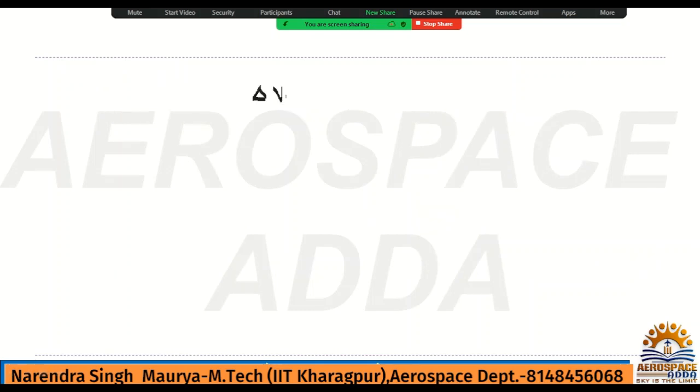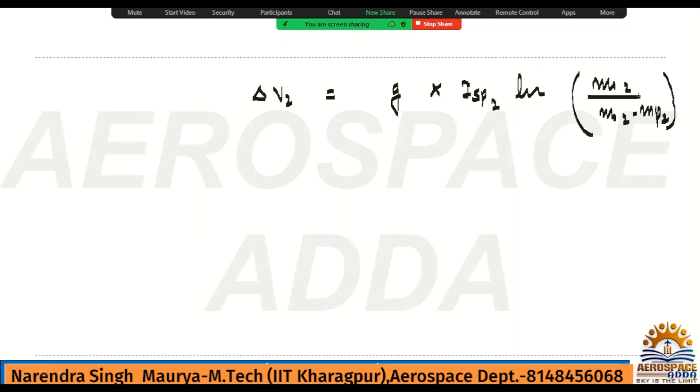Okay. Now we'll calculate delta V2 here. Again we'll do the same thing. It is nothing but G into ISP2 into ln of M02 by MF2, that is M02 minus MP2. If you write all the data here, G is 9.8. What is ISP2?